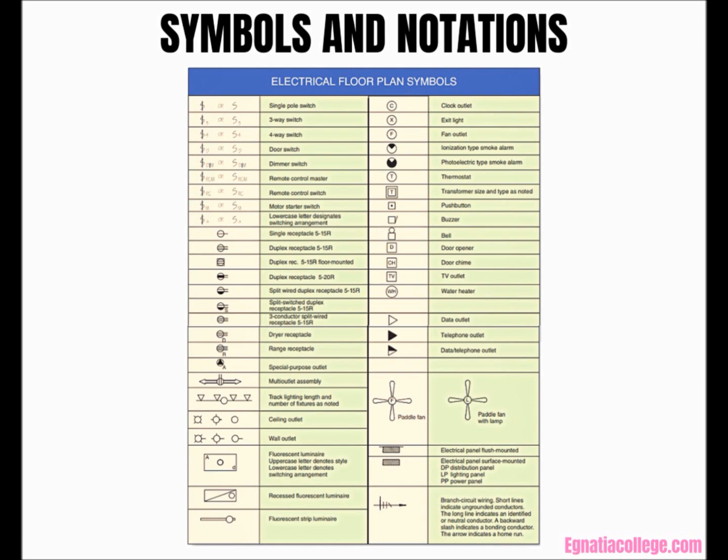Another method of using notations to avoid cluttering up a blueprint is to provide a system of symbols that refer to a specific table. For example, the written sentences on plans could be included in a table referred to by a notation. The special symbols that refer to the table would have been shown on the actual plan. If the word typical appears as a notation, it means that construction details are uniform throughout the building. An example would be typical 2-bedroom suite. This indicates that all the 2-bedroom suites are identical.